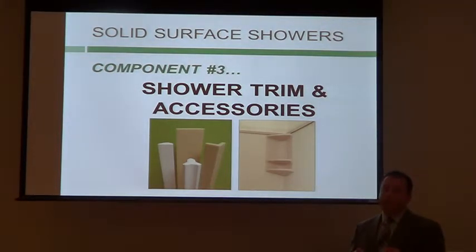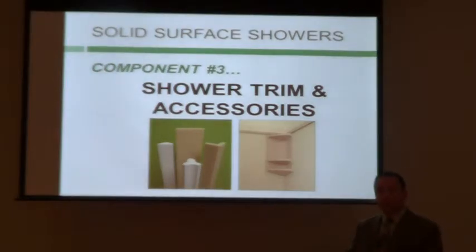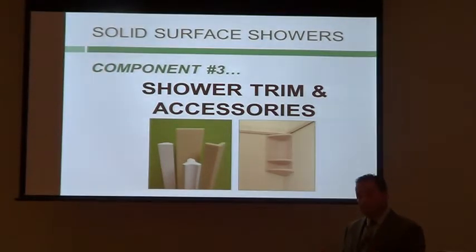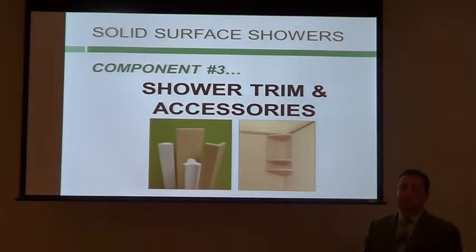Big benefit in a fast job site situation where you have a deadline, you need to get it done quickly, because you completely eliminate the upfront time and cost and the dust and the debris and the noise and the potential of maybe exposing some asbestos when you do the demolition. If the tile is relatively sound and intact, I can go over the top of it. But on the ends, in some areas, I might be able to see the tile behind it, right? That's where trim comes in.